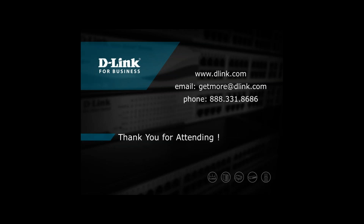Will BT be able to power external IR lights or illuminators for nighttime video? Yes, I believe so. AT and AF are powering IR illumination today. In some of my cameras at home, they're outdoor nighttime cameras, and at night they turn on the IR illuminators within the camera. But I know that there are some external illuminators that require even more power, and I would imagine as we get into 60 watts or 100 watts coming across that PoE connection, then certainly BT will be able to do that. So we'll stay tuned for that.